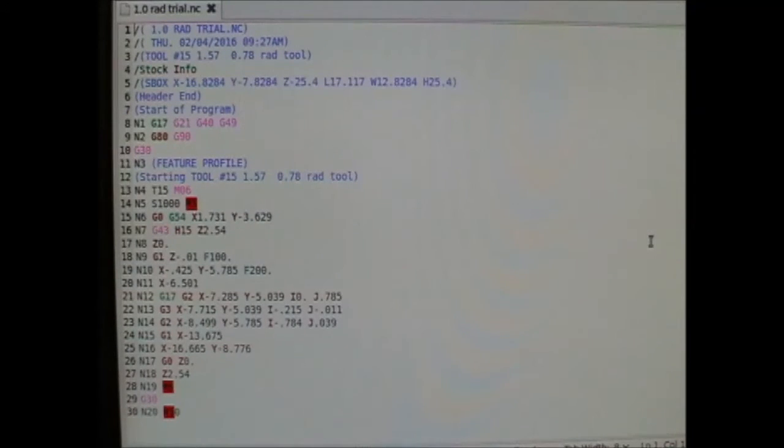First of all, I'm going to go through and remove all of the Z positioning, all of the clearance moves, rapid moves, the G30s and so on. That's easy enough to do. Then I'm going to go through and replace the X's with Z's, so that's the transfer of axes stage, and then finally the critical stage of changing around the arc formatting.